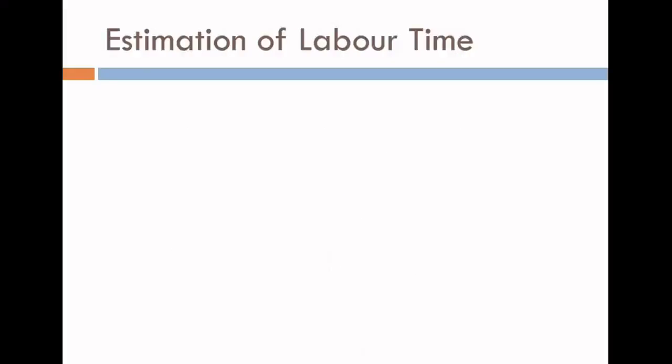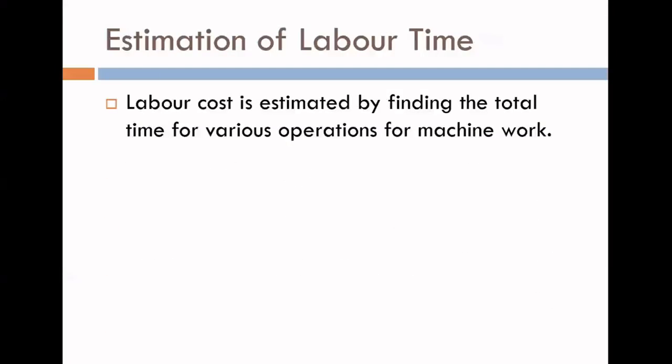The next point, estimation of the labor time. Labor cost is estimated by finding the tool time for various operations for the machine work. The first time is the setup time. It is the time required for setting, fixing and arranging the tools, machine and the equipment. It is denoted as T suffix SP.